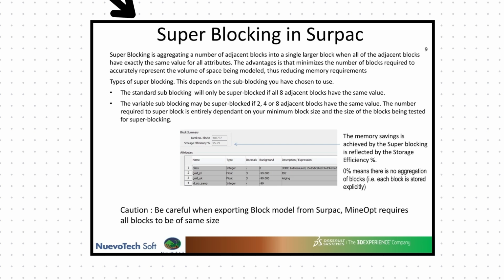The benefit is that they reduce the file size and give high storage efficiency, but they cost for optimization software like MineOpt. All blocks must be the same size. So after exporting, ensure no super blocking remains for MineOpt.